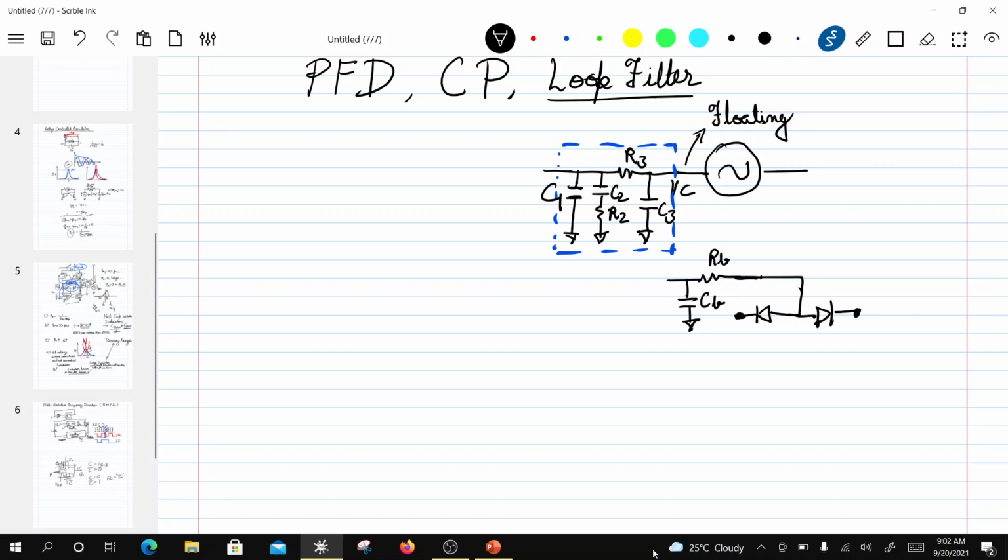Now if I look at this, so basically this goes in here. If I assume these diodes are not leaking any current, and I look at the diode characteristics, you would know that a diode behaves like this, and then it becomes asymptotic at a place which is your turn on voltage of a diode. Let's say that is phi 0.